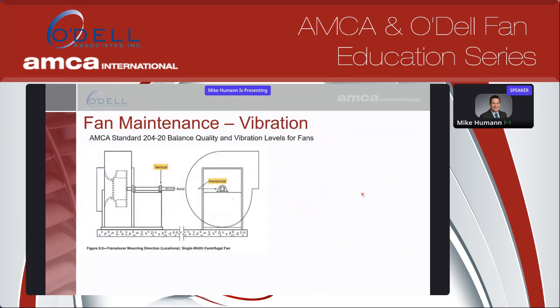So the last main fan maintenance thing we'll talk about is vibration. Vibration is really critical in fans, much like lubrication. Typically you see vibration measured in the vertical and horizontal on fans, from manufacturers. You do see some actual axial measurement. That's typically a little bit more of an aerodynamic plane, a little less predictable. It depends on what's going on in the inlet and what the pressures are. But vertical and horizontal planes on the bearings are your typical measuring points.